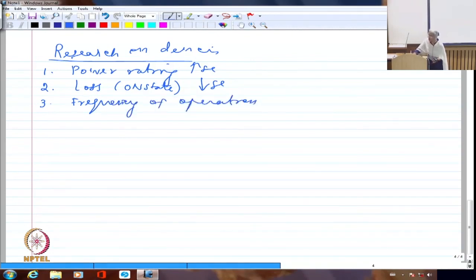However much we may say that it turns on in microseconds, it turns on in nanoseconds, we want to bring it down to 0, literally. Until now it has not been possible. If we are able to reduce the turn on and turn off time to really minimal, we must be able to go to 10 power 12 hertz or even more. But right now we are able to go until megahertz. Not really beyond that. So, if the frequency of operation of the device is increased, that means turn on and turn off is very quick.